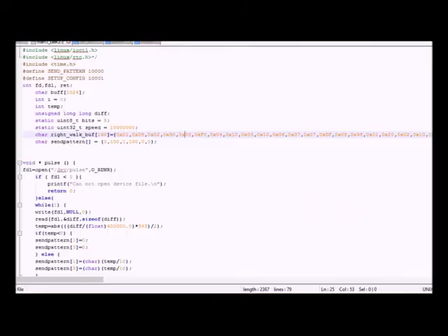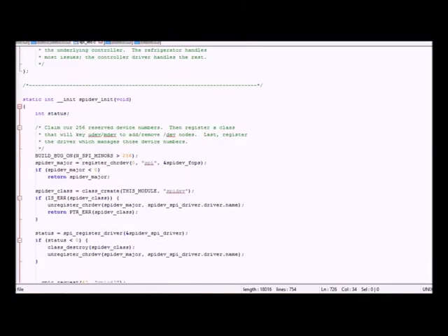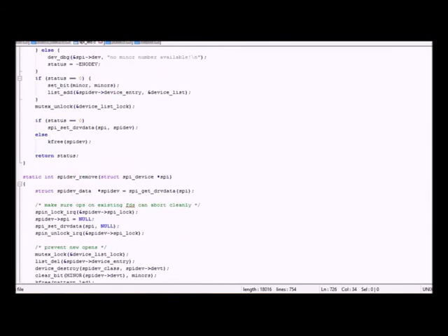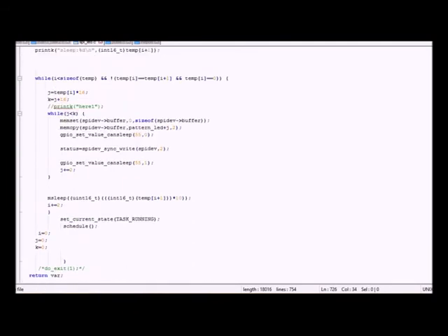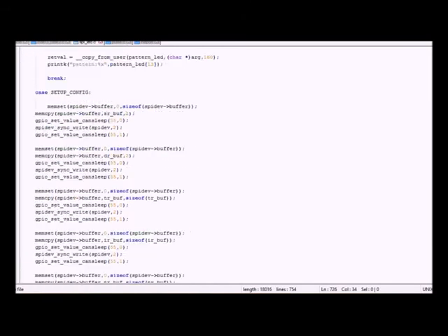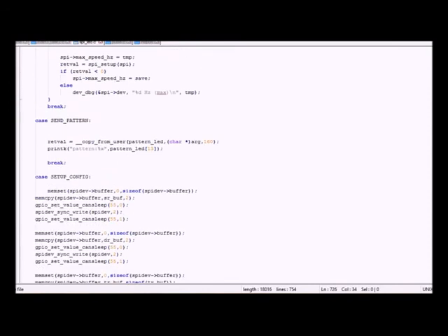So now we're looking at the SPI LED, and you see that we have set the 42, 43, 55 to the particular respective low values so that the SPI1 bus gets activated. And now we are going to see the IOCTL command that we use to transfer the buffer of 10 patterns. So here you see the test 10 pattern.